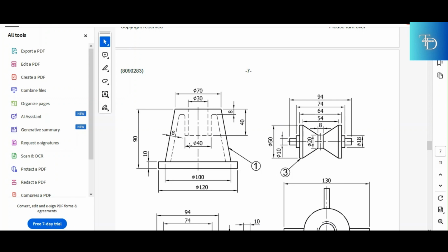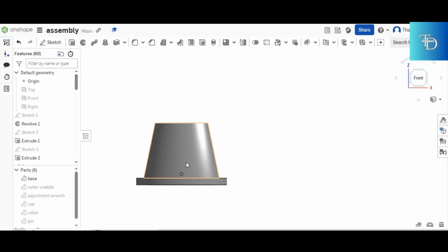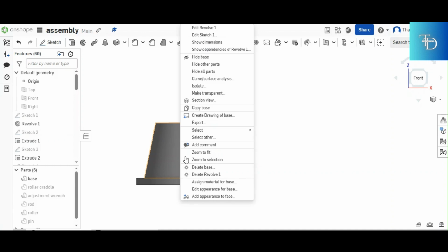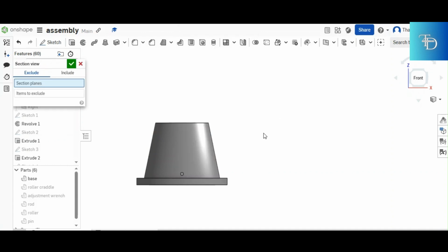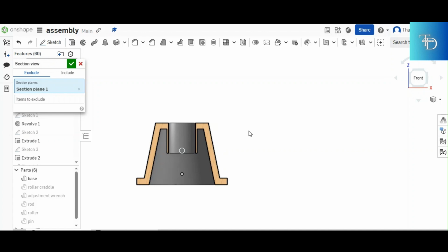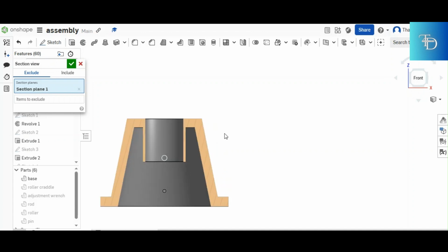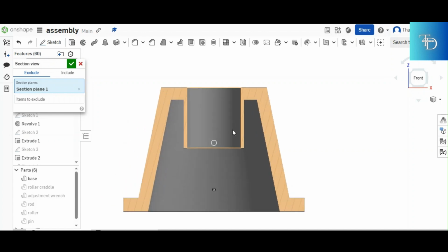Now, if you want to show the sectional front view, you use your sectioning skills. You imagine this thing being cut in half, and then how is it going to look from the front, whereby this outside part of the front view is gone? How does it look now? Let's go over and do that. All right, now here is our front view of the base. Now let's section the front. How is it going to look? It's going to look exactly like this. This is the front view.